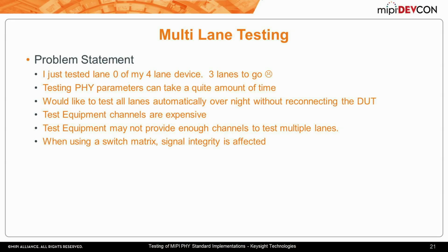All right, so let's talk about multi-lane testing. So let's say you've got a D-PHY interface, a 4-lane D-PHY interface, and you tested lane 0. Okay, you're all done. Well, congratulations. Not exactly. You've got 3 more lanes you've got to test. So every time that you have a new test or a new lane, or a new configuration, that potentially opens up an opportunity for